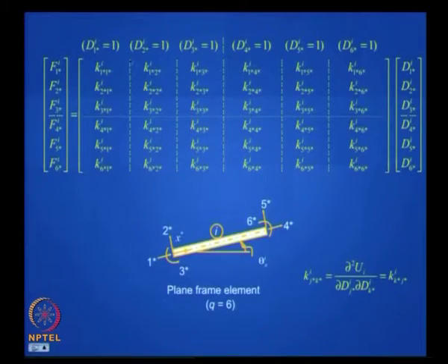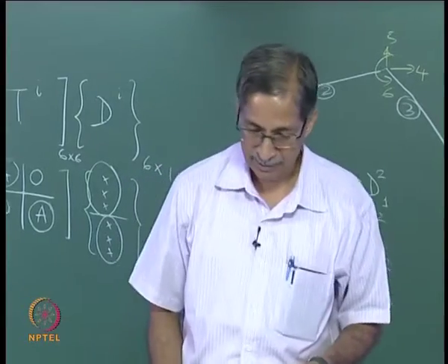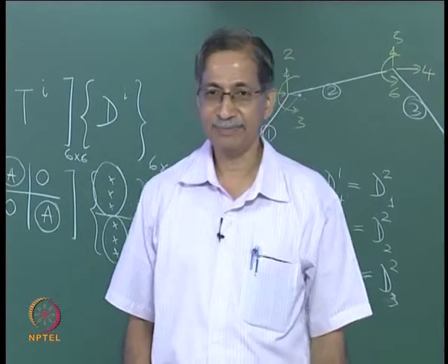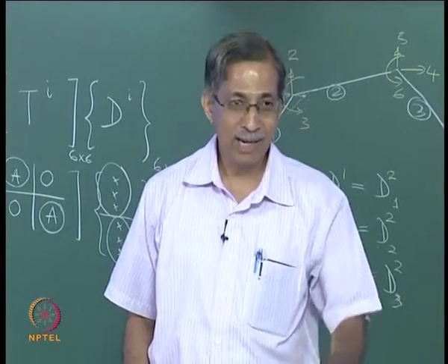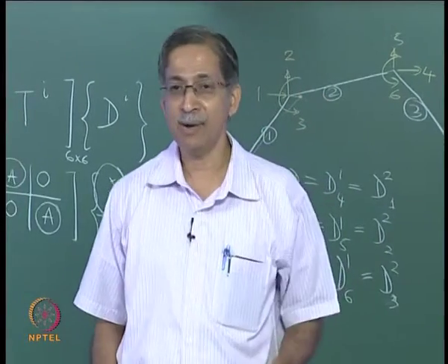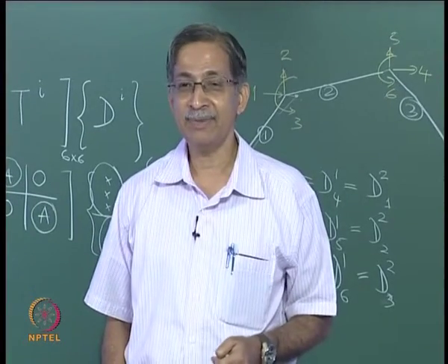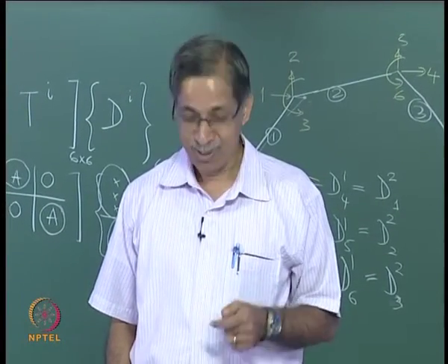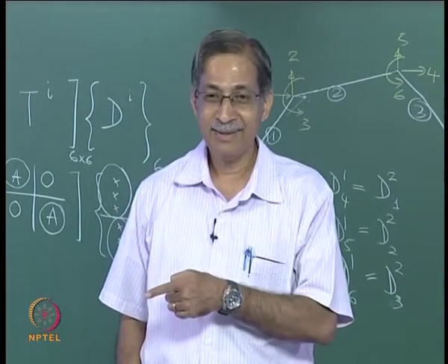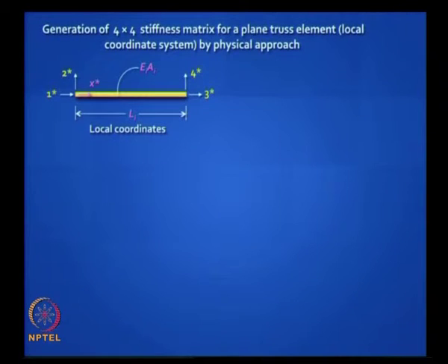And how do you fill these? You already know a physical approach. You can give one displacement, arrest the others, you can fill this up, but you can also do it using many other techniques including the energy method. We will see all this later. I am just introducing notation, I am giving you a framework how to do matrix analysis. Let us take one example, something you have never seen till now. I want you to generate right here, right now, in the midst of your yawning at 5:30 after doing a lab, I want you to wake up and generate the 4 by 4 stiffness matrix for a truss element, all of you. How to do this?